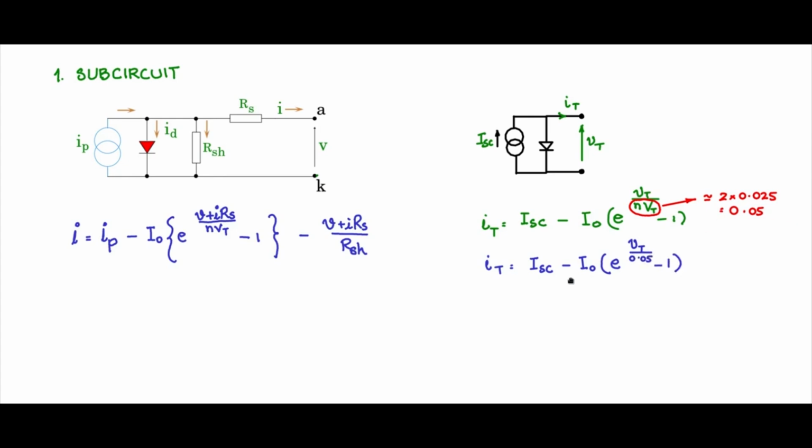So this will be the model of this simplified PV cell or PV module. Here you see that ISC, the short circuit current, is a value that we can set. So that is settable, and we can adjust that for module to module. What about VOC? We will see how we will adjust for VOC too.